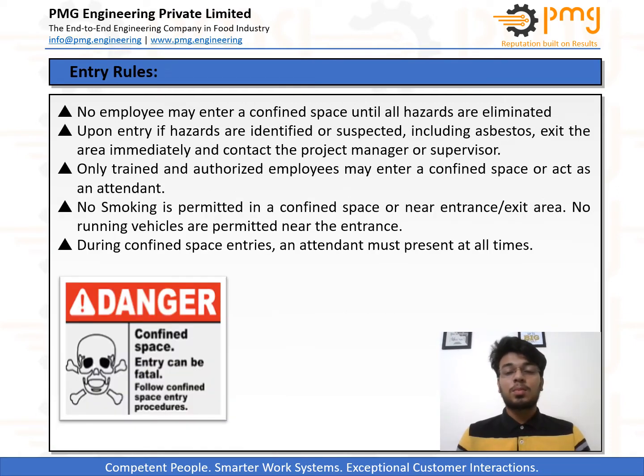Now let's discuss entry rules. No employee, even an entrant, should enter a confined space until all the hazards present in the space are eliminated. Post elimination of the hazards, if the entrant suspects some hazardous conditions to be still present, the entrant should abandon the site immediately and inform the project manager or the supervisor.